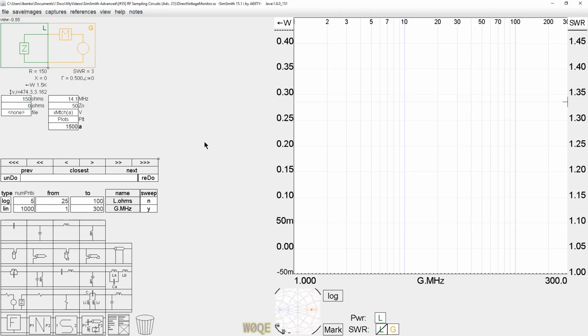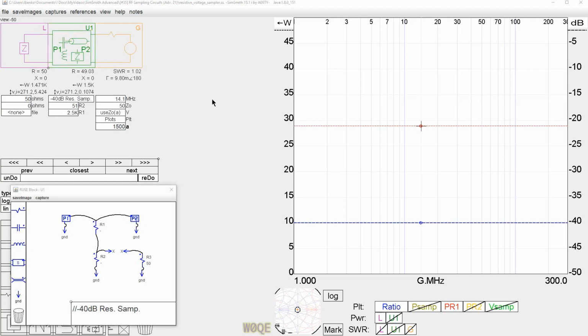So this kind of says to me that it's pretty obvious that a direct connection is a little bit iffy. Now, if you're running lower power, particularly QRPs, you're fine, and maybe even up to 100 watts, you're okay, but you have to look at your own probe and see what you've got. So the direct connection is kind of not really a good way to go, in my opinion, but it makes for an interesting discussion. Here's a circuit of a resistive probe.